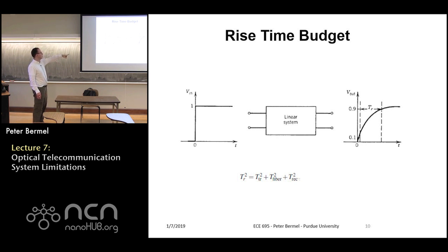So that means we also need the bit rate to be much less, hopefully, than this T sub F, which we calculated from here, right? If the bit rate, or sorry, I mean 1 over TX. I wrote it wrong. Sorry. So if the bit rate is equal to or greater than that, then basically by the time we turn on a bit, we're already trying to send the next bit, right? So then that becomes a problem, because we don't have enough time to send discrete pieces of information. It's all kind of getting blurred together. So that's another challenge in these designs.